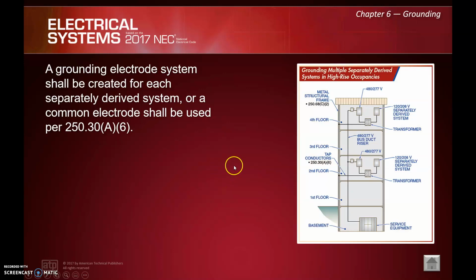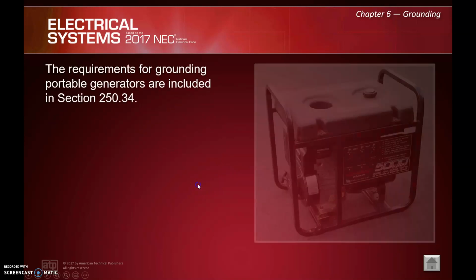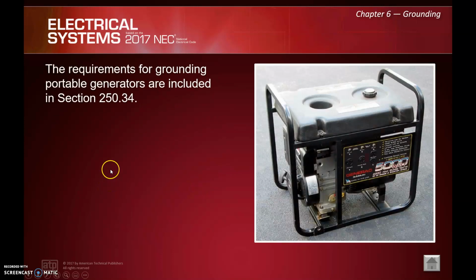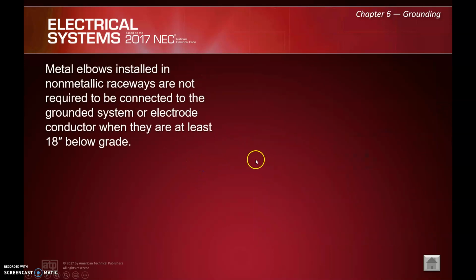That's what I mentioned on the first slide talking about separately derived systems. The requirements for grounding portable generators are included in 250.34. I'm not going to go into depth on that, other than to say there are actually requirements for grounding portable generators, believe it or not.